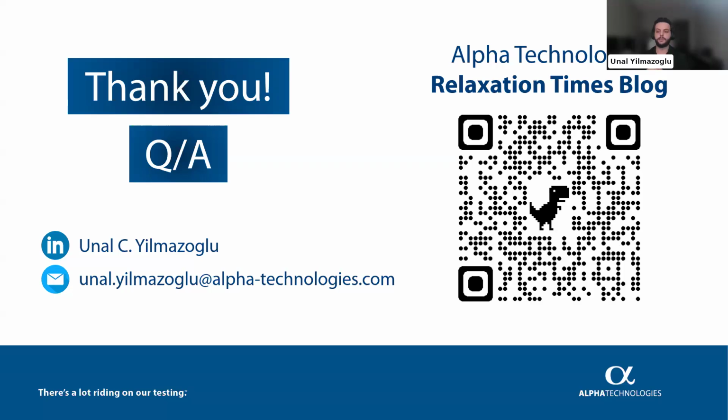Good question. Especially when it comes to natural rubber, there is a lot of heat history sometimes happening in the natural rubber. So what I will do is condition at 50 degrees C for a couple of minutes, like 4 or 5 minutes, and then ramp it at 5 degrees C per minute slowly to erase that thermal history and go up to around 150 degrees C to get a more effective cure temperature determination.